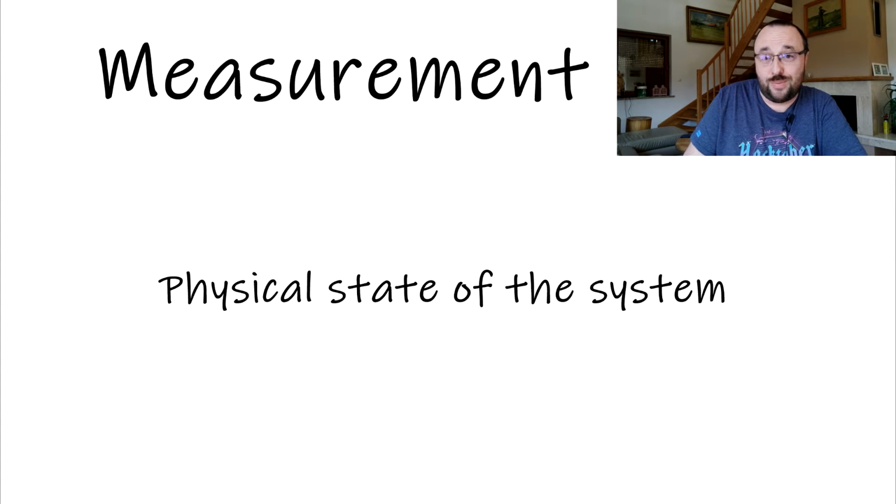Now, when we know what the feedback loop is, there are three terms that everybody has to understand. The term number one is the measurement. Yes, the measurement is something that goes out of the sensor, like the gyroscope, thermometer or flow meter or the anemometer or whatever else. And this is the information about the current state of the system. In case of the multirotor drone, it's the information how fast it's rotating around one of those axes.